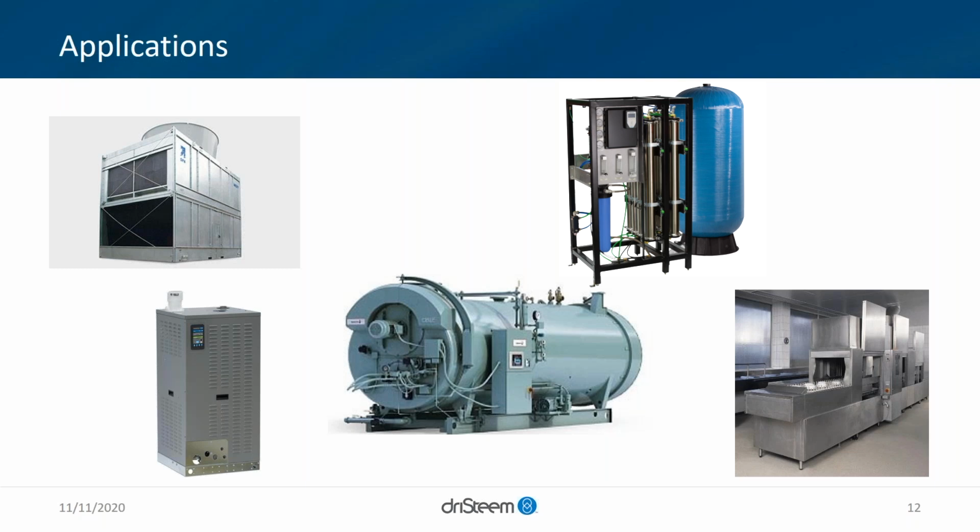In the center of the screen, a depiction of a steam boiler. Again, this is an industry that has accepted softening for the most part on steam boilers, on the pre-treatment water, essentially maximizing their fuel usage, because scale increases their energy use and their operating cost.